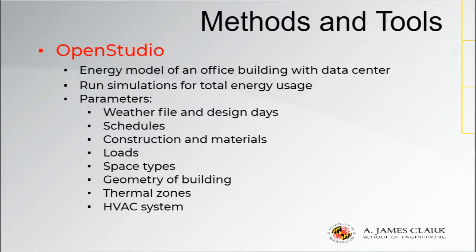As mentioned, we used OpenStudio. It's software where we were able to create an energy model of an office building with a data center. We were also able to run simulations in order to find the total energy usage for each of the parameters that we have set. The great thing about OpenStudio and modeling in general is you can input a plethora of variables, some of which we have listed here, such as weather file and design days, schedules, constructions, and materials, etc. Not only do you see how these variables affect the overall design, but how they affect each other. This will not be possible with traditional methods because it would take far too much time and money.